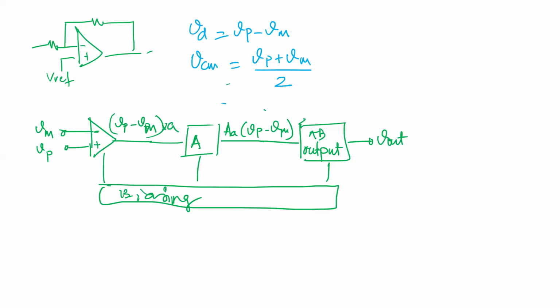And the reason you divide by 2 is because, let's say these voltages were the same, then Vp plus Vm equals, let's say, V plus V, it will become 2V, right? But actually it's just V, so you divide it by 2. And if one of them is higher by delta V, another one is lower by delta V, they get cancelled out, you get V. Okay, so it's just capturing what's the common mode. Okay, I'll draw a sine wave just to show you what it means. All right, so these are the two main definitions of this thing.